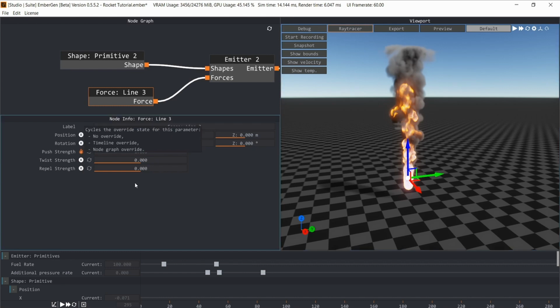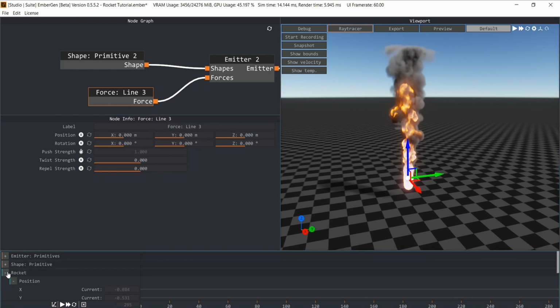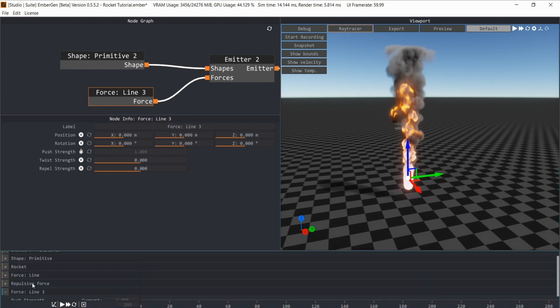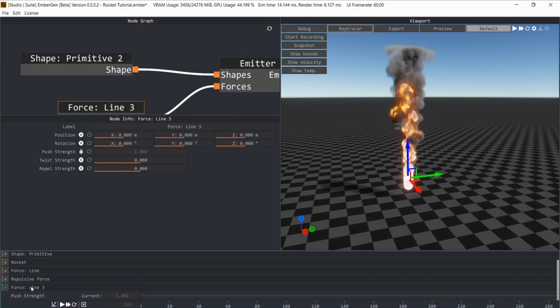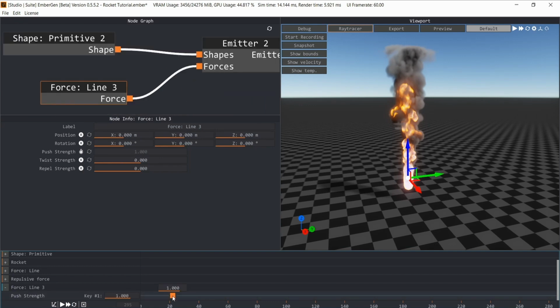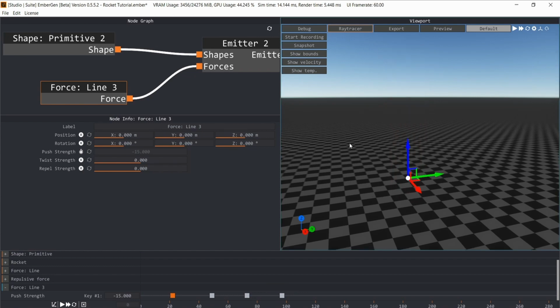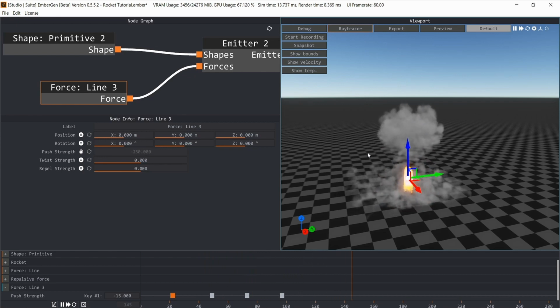We press this button to start the keyframes. So these are all the ones from the previous nodes. The keyframes that we'll be creating now will go below. And then right click here and I'll enter -15. Go forward a few frames, enter -500 and -250. Now let's look at what happens. So it starts, it goes downwards, hits the floor, and then starts to widen.